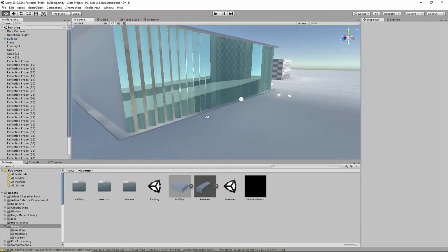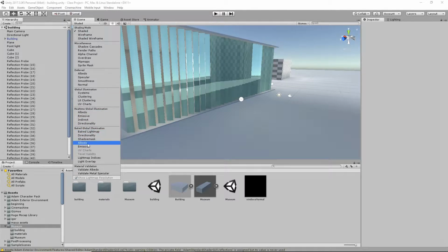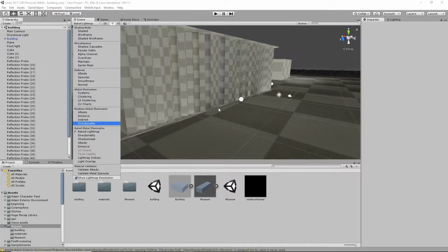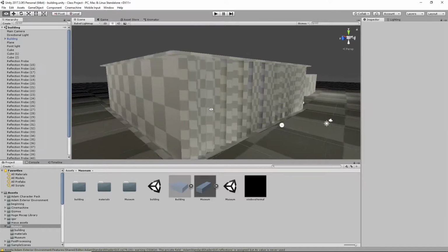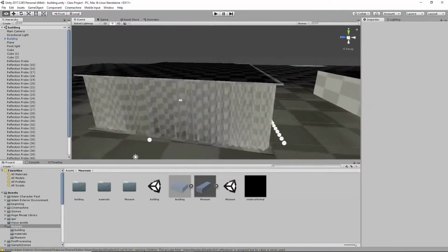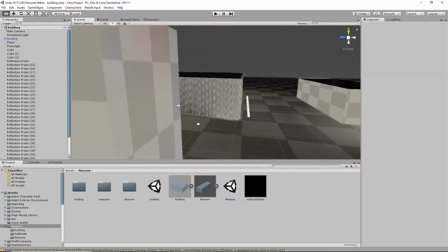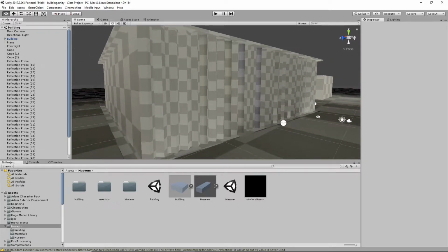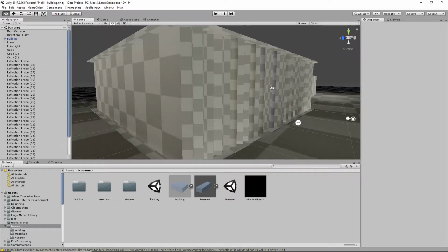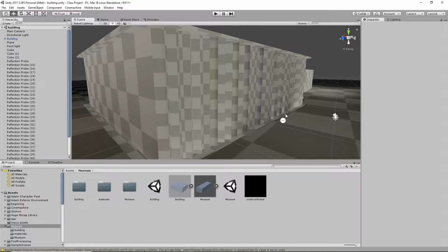But once it finally baked, you can check it out in the actual baked light map. I went and reapplied UVs across all the objects, especially the planes, which I probably should have done first anyway. Don't pay attention to all these reflection probes. I added those as well to illustrate the difference and how to set up reflection probes for more realism, and the cost. The first thing I did was modify all of these fins. If you recall, I'd already modified this first one, and the other ones.